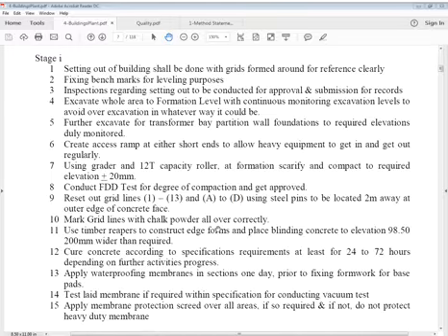It is a very important point for everybody. When you do machine excavation, not the manual excavation. Nowadays manual excavation is not generally done, but machine excavation is done for everything. We use JCB or some excavator, and generally the teeth of this bucket are so strong, and its volume, that over excavation chances do exist. So it's better not to. You leave the last layer, a very small layer, say 10 centimeter, 20 centimeter, which can be covered later on. Otherwise, if you excavate more, it becomes a problem.